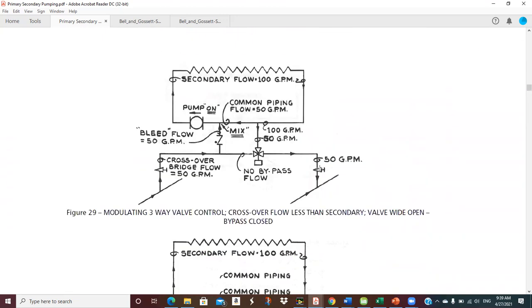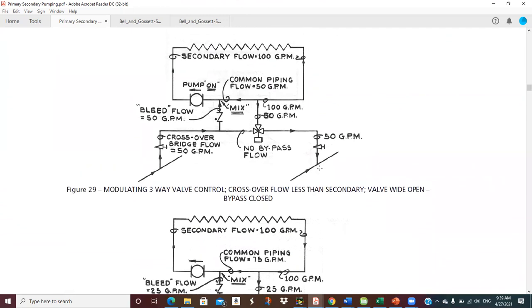But in a heating situation, then I may well be doing something like this, where because I can make this water super hot, then I can downsize the pipe and downsize the flow, which saves me money on building the system. And then I can take that super hot water and just mix it here. Because if you put too hot of water in this coil, it makes it hard to control. Then you're probably going to overheat people. Or you can make air so hot that you could burn somebody if they brushed up against a register, and you wouldn't want to do either one of those.